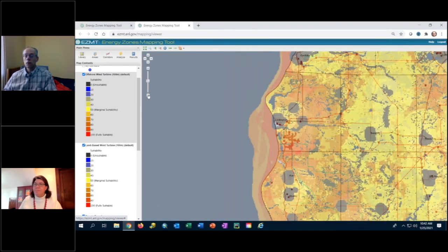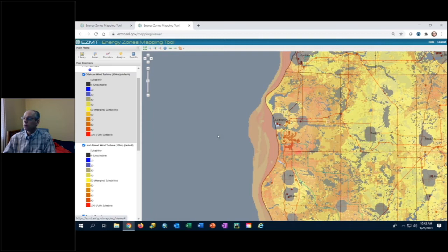But here's that. The offshore wind, one of the factors is the depth of the water, because once you get beyond a certain depth of water, then you've got to maybe put an anchor and have a floating unit, and of course you need to connect to an onshore substation that's within range, so the cost would go up the farther offshore you are. But that's just one of the siting factors offshore. So that's why we have different models between the land-based and the offshore wind turbines.